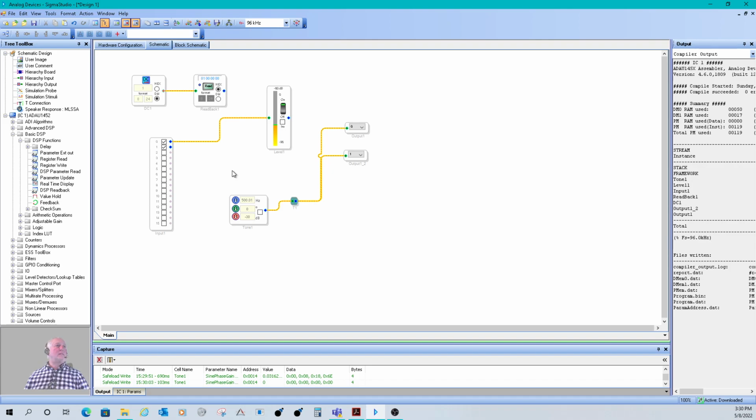And as a side note, I don't know how many videos I'm going to do for the Sigma 200, but the 1761 has a kind of an odd way. What happens when it runs out of MIPS is it just keeps going and ignores an interrupt, and so it ends up processing every other sample. So in the end, it acts like it's running at half the sample rate.